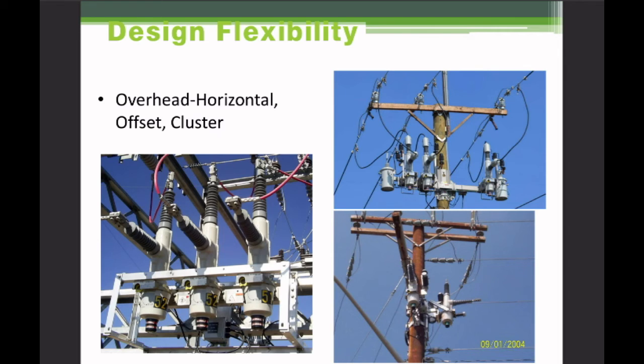That's done in software. This one here is wearing some animal guarding. These units out to the side are potential transformers. So you'll find one of these terminates to this side of the switch. The other one's going to terminate to the other side of the switch. And so now it knows what the voltage is on this side, and it knows what the voltage is on this side, which allows the computerized equipment that drives it to have some extra ideas about whether there's voltage on either side.